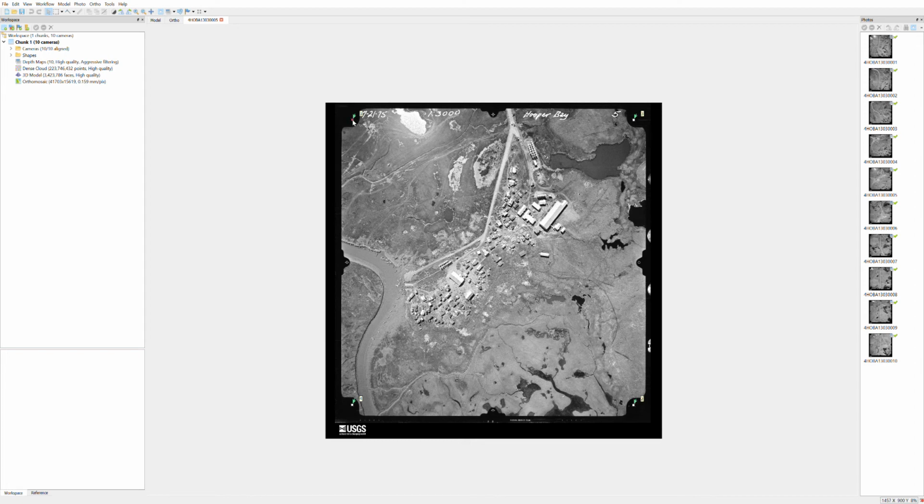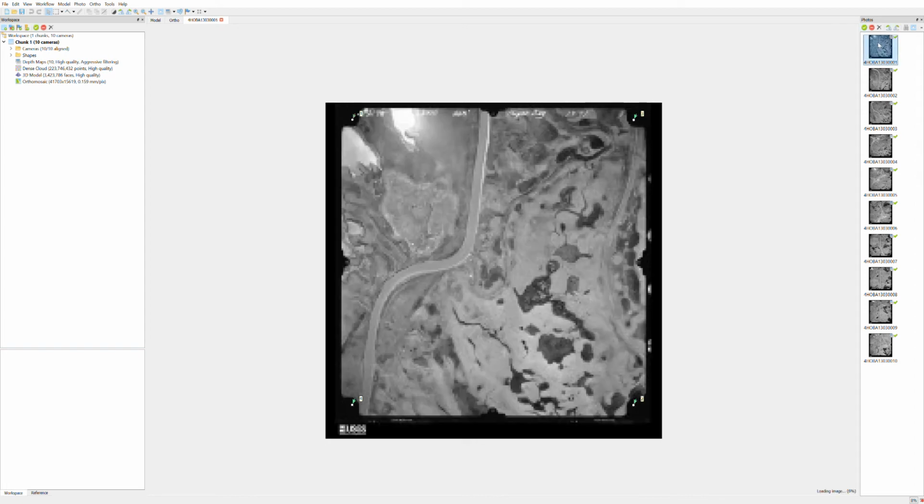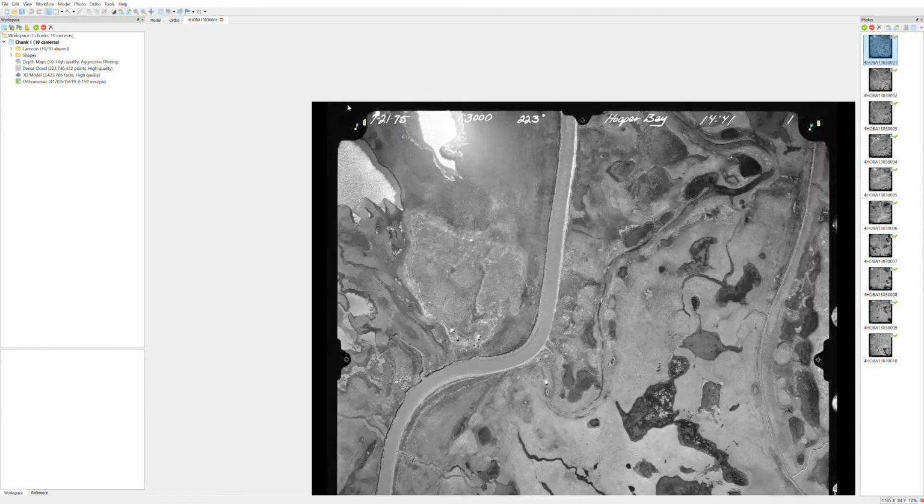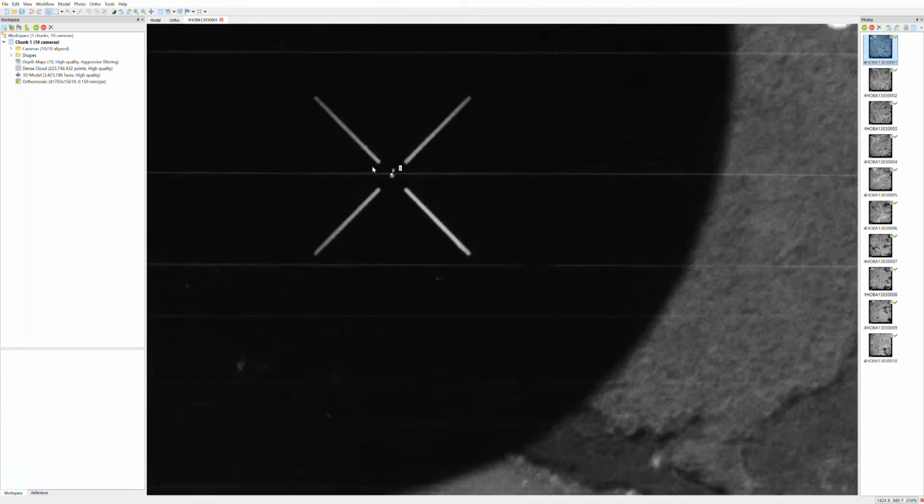So then the next step is to identify the location of your fiducial marks. And I'll just go to my first image here, and in this I've already identified them, so you can see 1, 2, 3, and 4. But to do that, to start placing them, just zoom in to the top left X, start on the top left, and you'll want to right click and go to Place Fiducial, and then select New Fiducial, and that will just automatically generate number 1 for you.